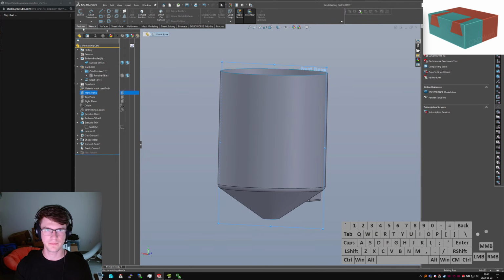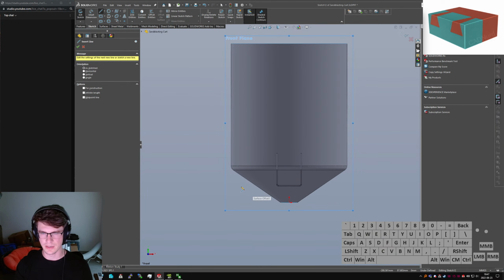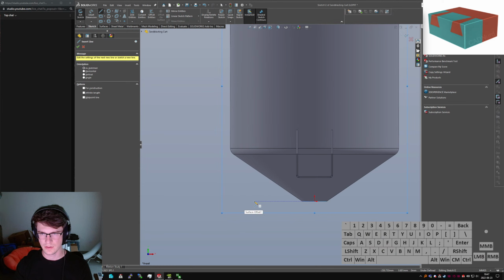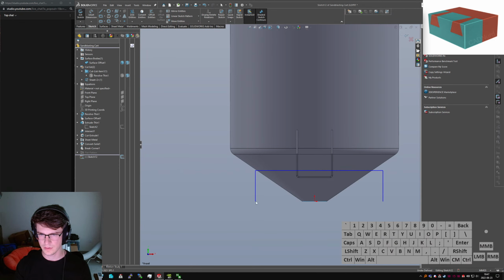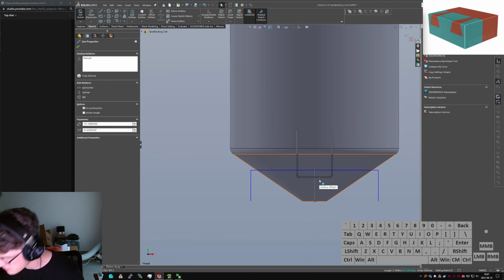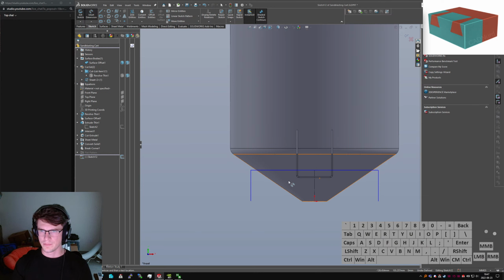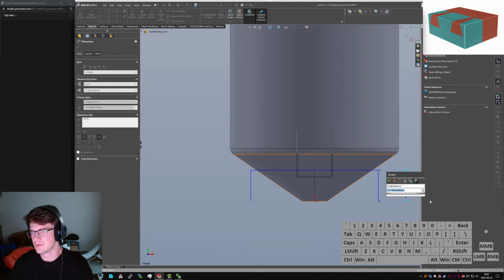So we're going to start from the front plane, sketch, and let's see, need to come up here, over, down, go from the center line there, up, vertical. Is someone sending messages? No, okay, we're good. How far? Let's say that this needs to be 150 millimeters.